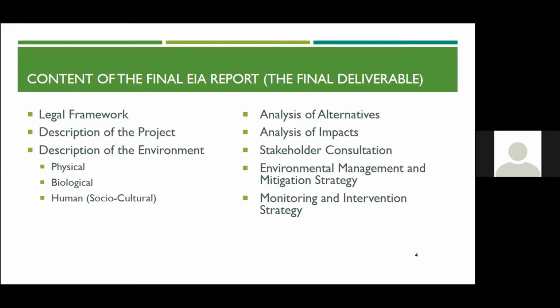Right, so the final deliverable of this project is the actual EIA report. So the contents will include the following. The legal framework investigates all the local and international standards and guidelines governing the environmental quality, health, and safety that the project must be in compliance with. Local standards are going to be used to place these results in context. Some of the local standards that we use are the water pollution rules and the air pollution rules. And in the absence of local standards, international standards are used.